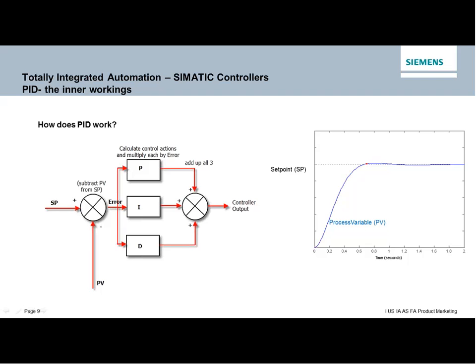What's the result going to be of that? We're going to see a drop here. It's going to suddenly drop very quickly because we're using a huge amount of air that we were never tuned in for, just the paint booth part of this. Derivative will see that error happen, fight that rate of change, and turn up the air compressor. D can be very handy on applications like that where we have everything tuned in very nicely for P and I, but then there's a change to the system. D is very helpful with that.